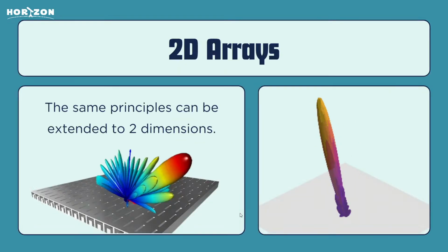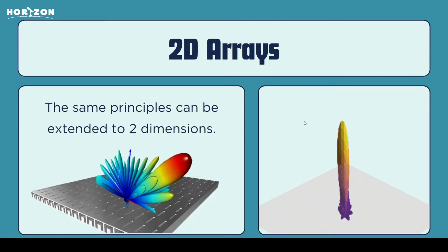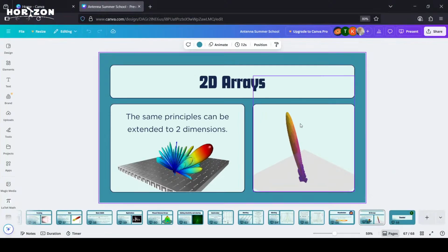Yeah. So one more thing that is a natural extension of these antenna arrays is a 2D antenna array. All of this discussion was happening in just one dimension. These antennas were all lined up in a single straight line. If I have a 2D array of antennas, say a square of antennas, all situated at certain particular distances, then that gives us beam steering in two different angular directions. So we can look at any part of our environment or any part of our sky with very nice precision and nice directivity in some sense.